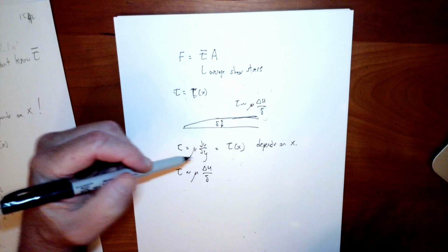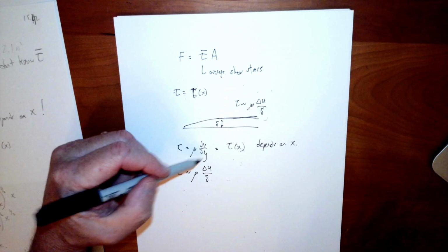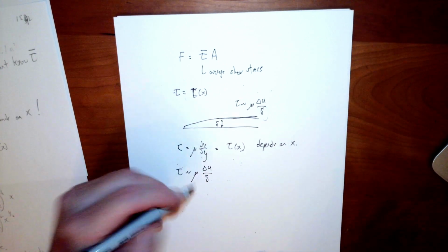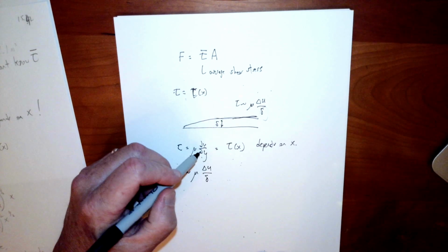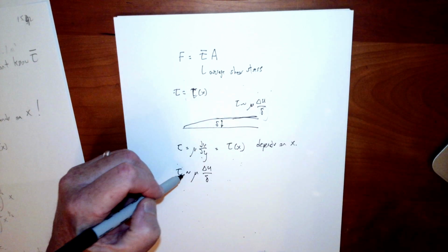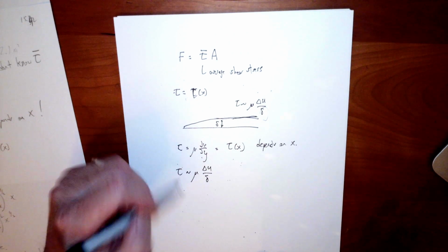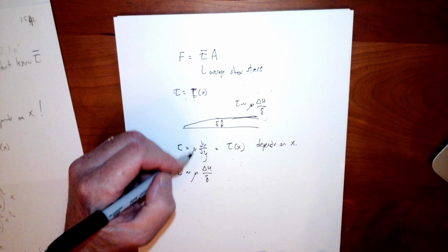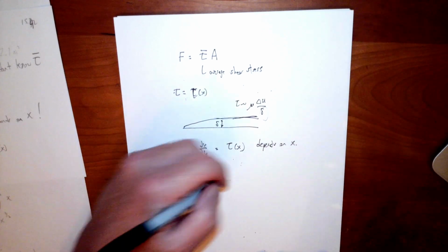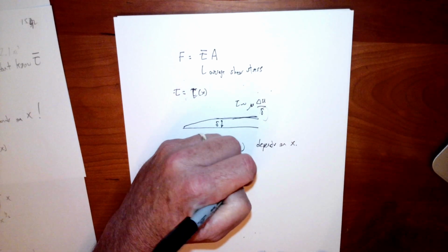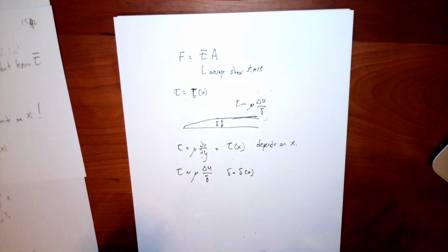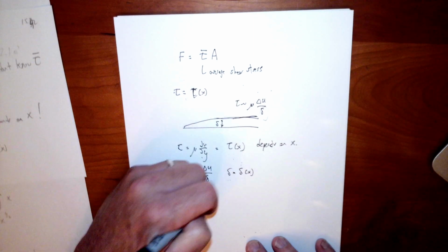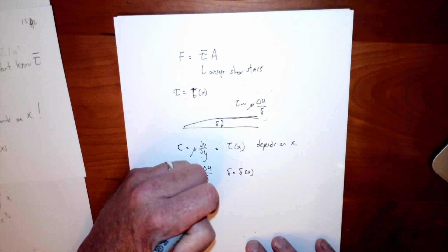So tau is of order mu delta u over delta. Notice I've changed from equals. This is the true definition of the shear stress. When I replace this du dy with delta u over delta, that's not the derivative. It's an approximation of the derivative. So I can go to the order sign here, or an approximate symbol, but I need to recognize that I've switched from truly being equal to being an approximation. And I know that delta is actually a function of x, which is why tau is a function of x. So I know the form of that because delta over x is equal to 4.92